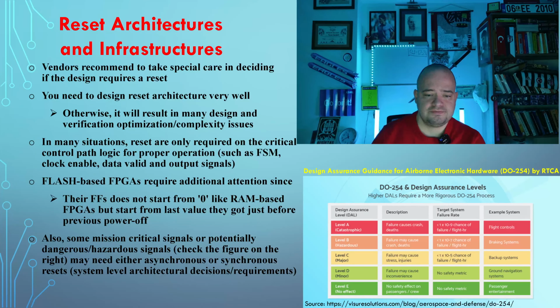Let's say the clock circuitry, the clock IC, is somehow not working, because synchronous reset requires a rising edge of the clock. If you somehow cannot provide a rising clock edge, then of course in case of an emergency you cannot stop that critical signal.